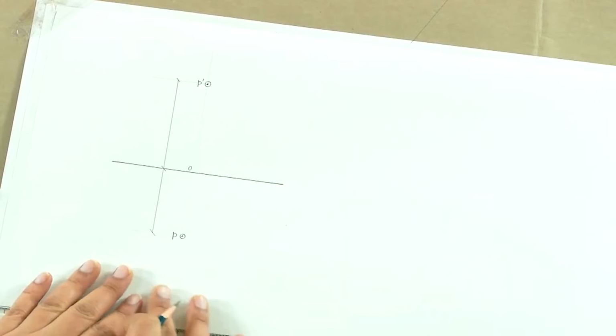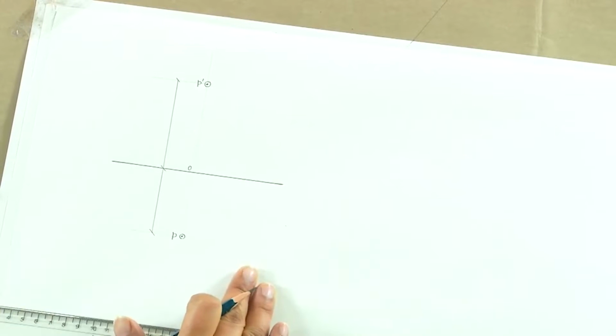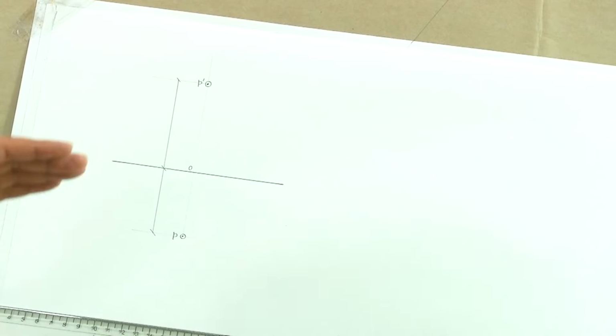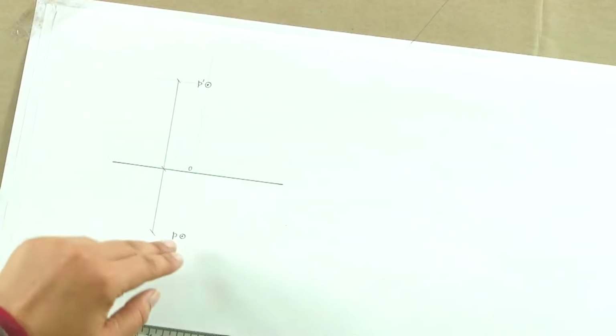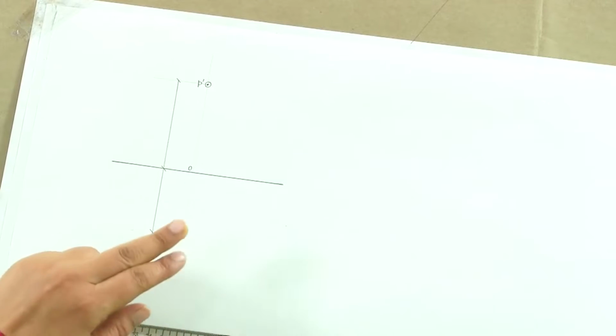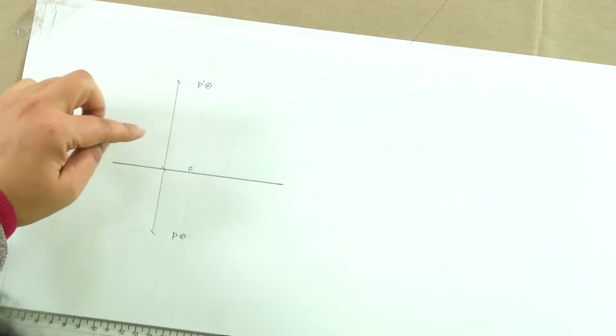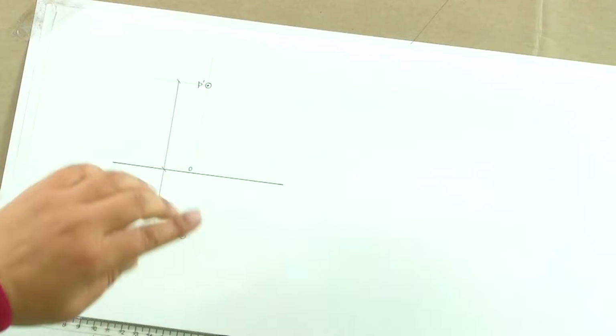If you remember, we always had to mark the dimension towards the left preferably and to the bottom. Now there is no horizontal dimension which has to be shown towards the bottom of the drawing. So we just have this. Now, you always have to remember, the distance from VP is shown in the top view and the distance from HP is shown in the front elevation. Often we make mistakes about that.